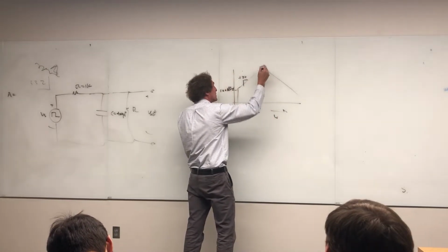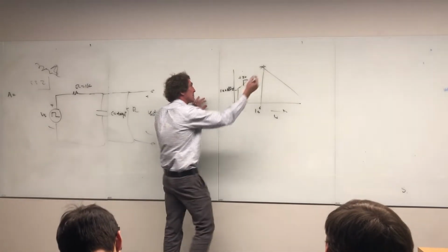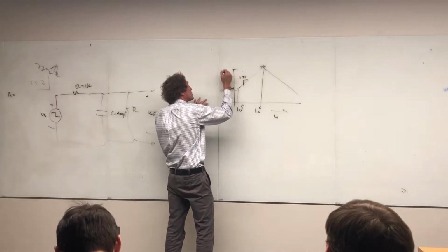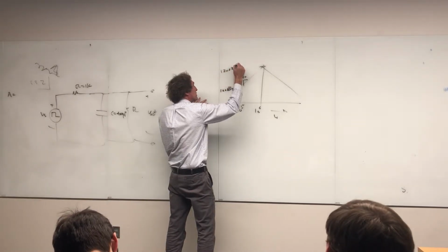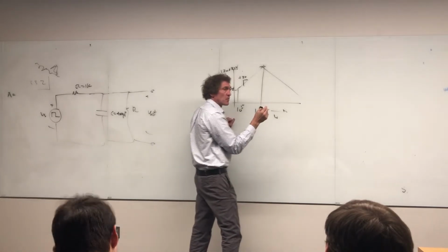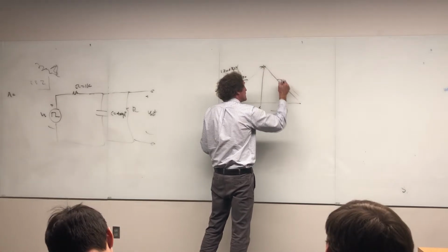And here, you can figure that out. That's one order of magnitude, right? Going up by 20 dB, that means this is going to be 100 plus 20 or 120 dB microvolts, right? You should have that on the caption. Yes. Then it starts going down, 20, or is it 40? Minus 40. All right, so now this one's going down at 40 dB.